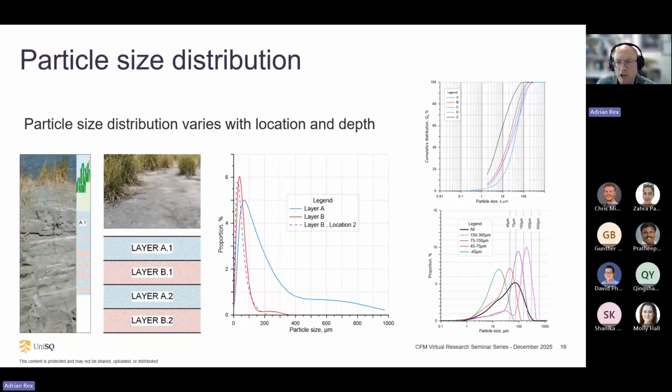Again, sedimentation theory. If we look at the particle size distributions, and yes, I know this graph's difficult to read, you can see there's quite a wide range of particle size distributions between the different ashes under test. So in an ash pond, there's a long ash pond, pump in there, we see different particle size at different locations within the ash pond and also at different depths within the ash pond. So an ash pond is not homogeneous.